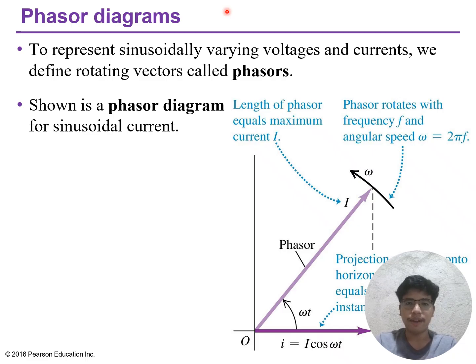The beautiful feature of the phasor representation is that sinusoidal quantities with the same frequency can be combined by simple vector addition in the complex plane, transforming what would otherwise be a tedious trigonometric manipulation into straightforward geometry. When we combine phasors representing the voltage across different circuit components, we need only add them as vectors, automatically accounting for their phase differences, a process far more elegant than trying to manipulate the original sine and cosine functions.